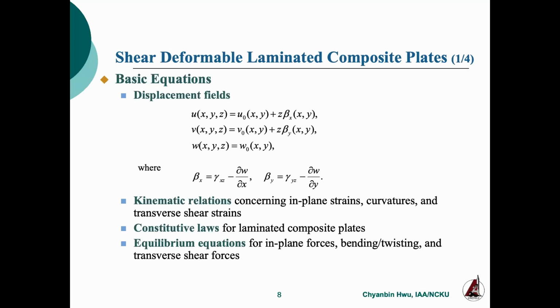They are related to the transverse shear strain. So we consider the transverse shear strain for the thick plate. The kinematic equation will concern the in-plane strain, curvature, and transverse shear strain. We say that the bending and stretching are coupled to each other. And the constitutive law is the usual law for the laminate composite plate, and the equilibrium equations are for the equilibrium between the in-plane force, bending, twisting, and transverse shear force.